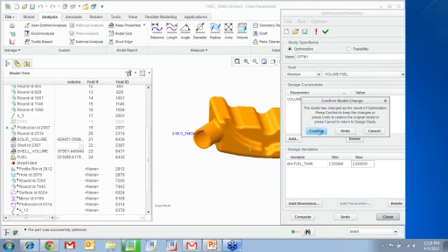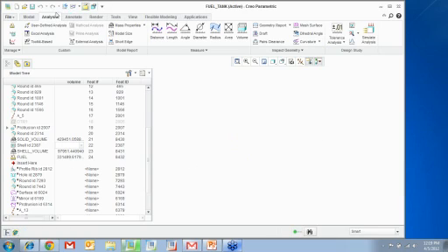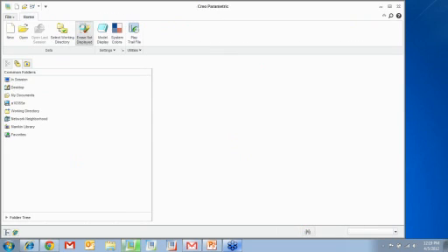So if I close it and confirm, notice it tells me that's pretty much what my volume is. Now you see that you can increase the accuracy level of your part and you can get to more zeros, or get closer. You can increase the percentage of convergence of your optimization to avoid any kind of errors like these. You can say, I want to have a percentage of convergence of 1%. So allowable error is 1%. So it's going to get much closer to 330,000 exact. So anyways, that was volume analysis.